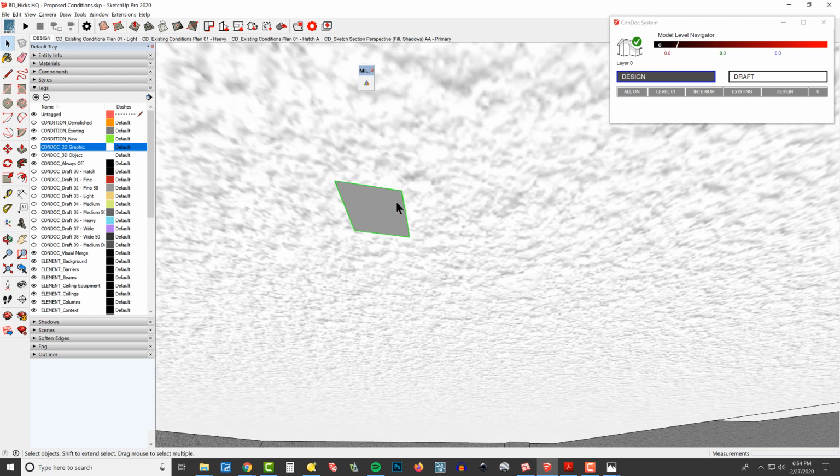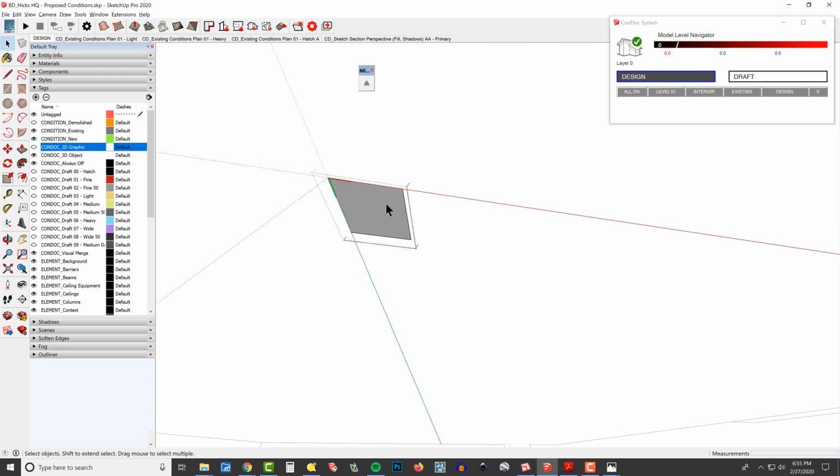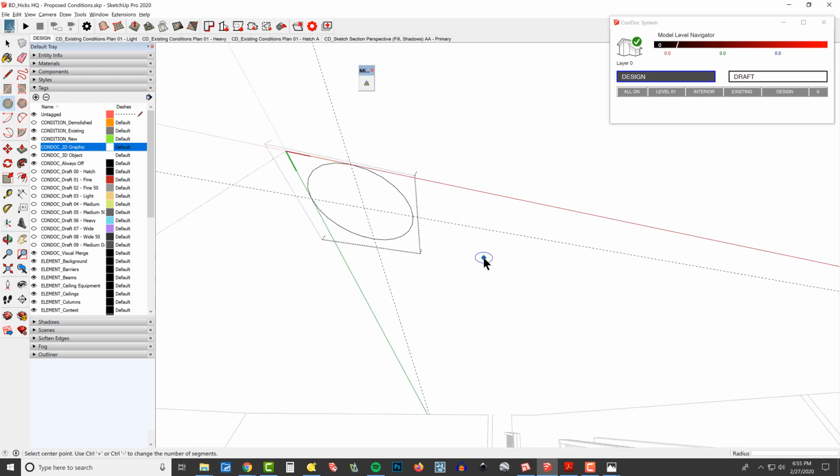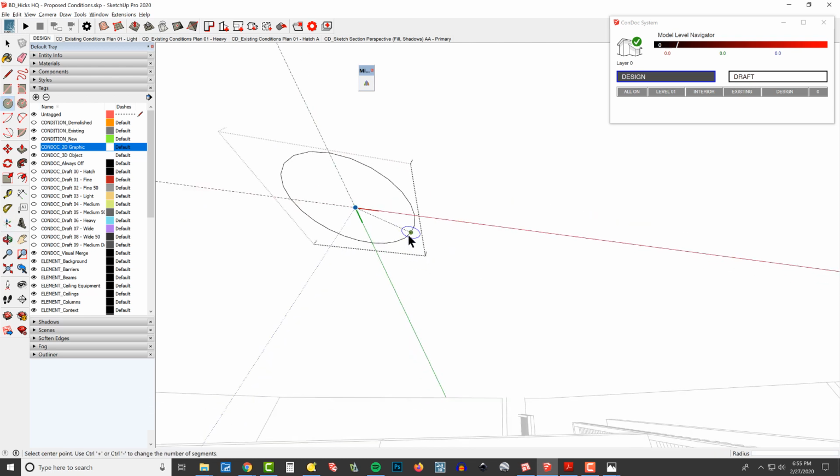I'll create it, and then I'm going to double click, and I'm going to draw a circle. Really what I want is, I guess I would just draw my guidelines like this, and like this, and I could have just drawn a circle, I suppose. That would have been easy enough, which would have been 25 millimeters, like that. All right, and then also on this downlight, I'm going to right-click and hit Change Axes. I want my axes to be right at the middle, like that. And then I would probably offset it.